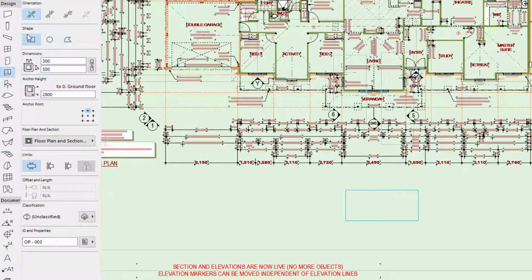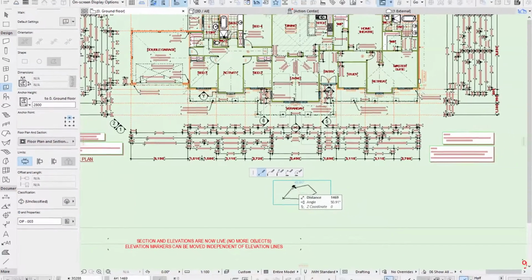I can create a rectangular opening, I can create a circular opening, now I can create a polygon opening. You can see with the rectangular and the circular it has the sizes, with a polygon it has no sizes. So I can create a polygon, single lines, in any shape, move that out of the way, in any shape that I want, in that slab.